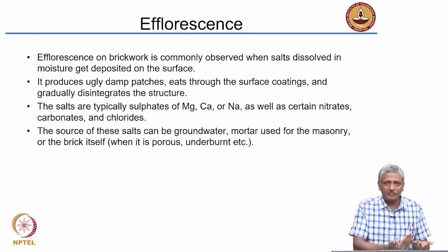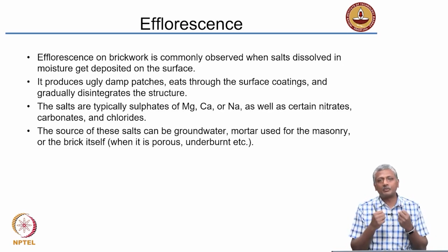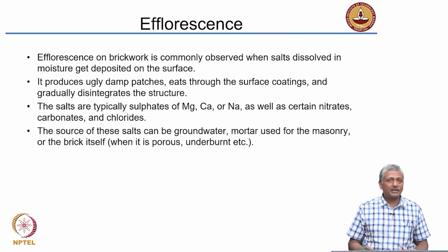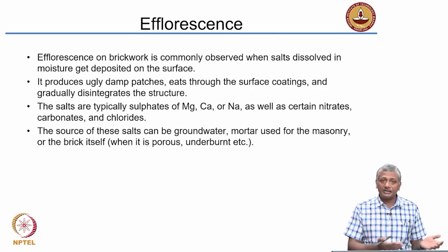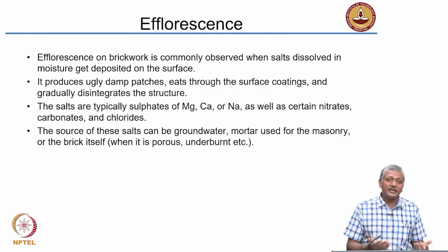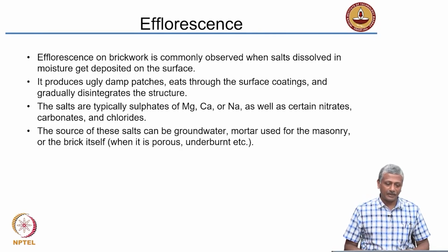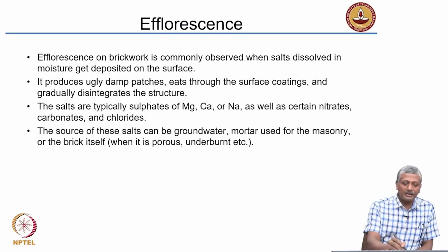Why are the salts getting into the brick in the first place? Because bricks are absorbing moisture from the outside. Are salts present inside the brick? High possibility is there, because of the water that is used to mold the brick, and because of the clay that was originally used to manufacture the brick, that may itself have some salts in it. Okay.